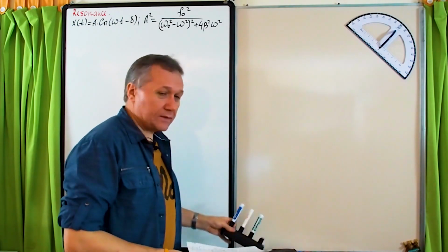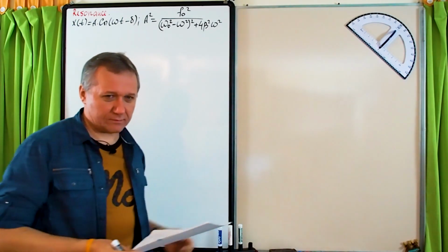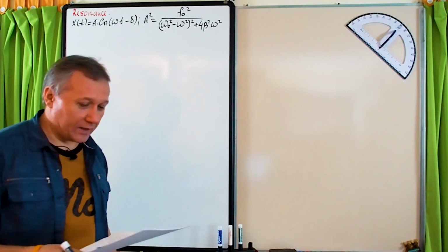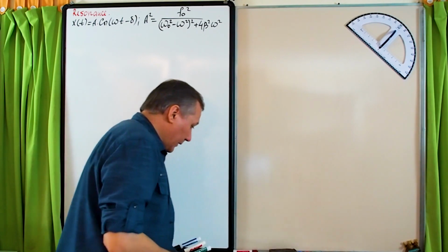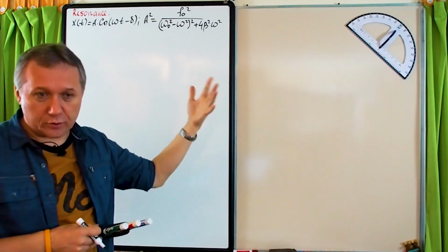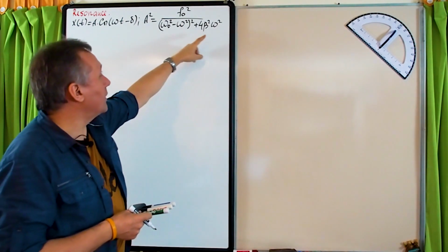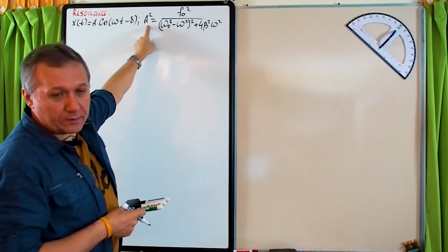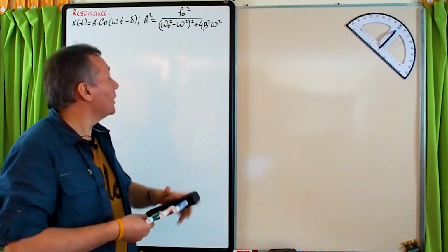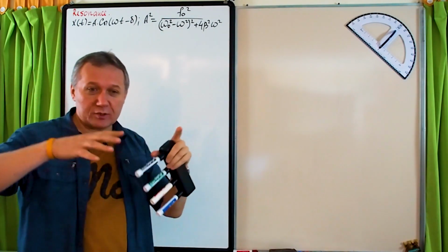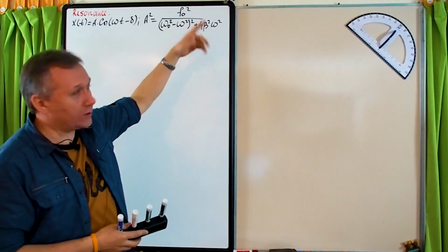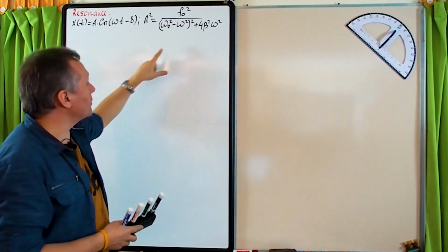The delta, I will write it maybe in 15, 20 minutes, because only then we will start discussing it. And so this is a function of omega, so it makes sense to search for a value of omega where A is the maximum. Again, how are we looking now at the system? We assume that the system is given, so natural frequency is given. The system is exposed to a certain medium, so beta is also a fixed constant. So everything is constant except for omega.